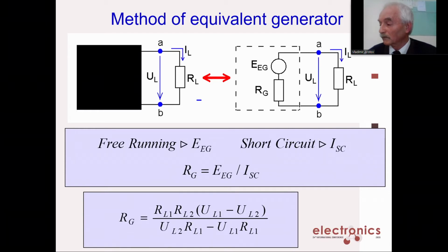However, as will be shown in the concrete diagrams, in this form the equivalent generator method is not applicable for the analysis of our circuit. This is due to a feature of the step recovery diode. In the absence of an input pulse, a forward charge pumping current flows through the diode, leading to charge accumulation. The resistance of the diode is low.